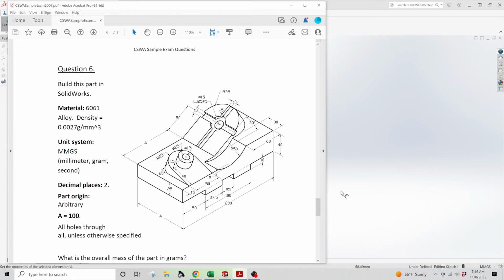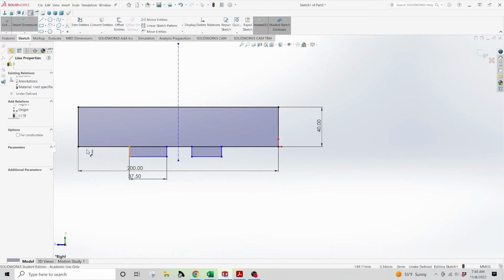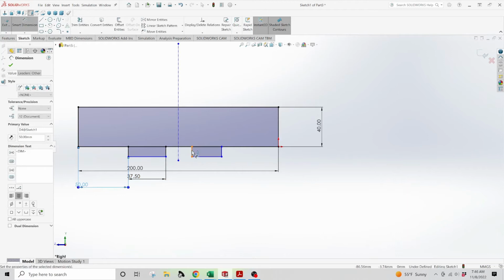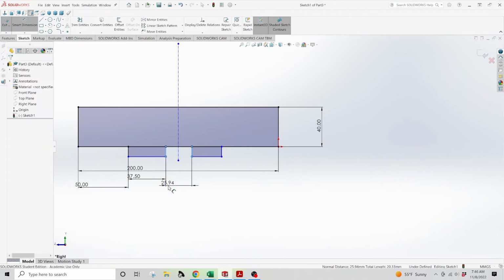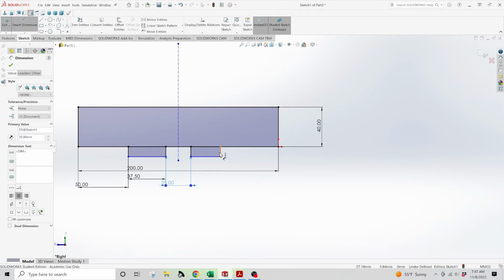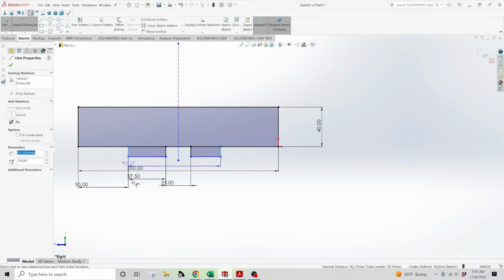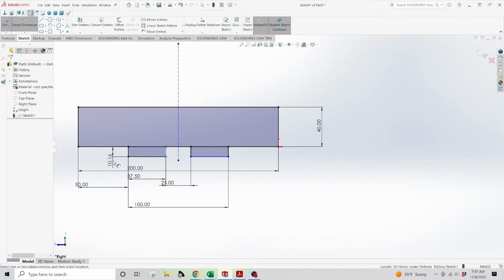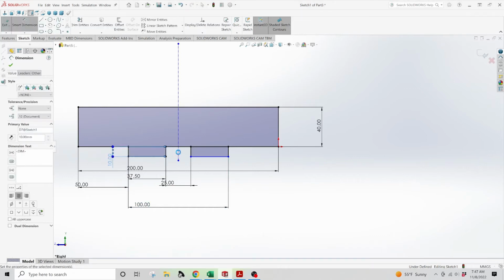This edge is 50 millimeters from that edge. So here to here should be 50. So we're close, but not quite. This separation needs to be 25. So again, we're close. And this edge to this edge needs to be 100. So again, we're close. All right. So those two do appear to be the same size, and they should be based on 75 divided by 2, but you want to double check based on other references because they won't always give you nice symmetry in that way. So that's an important aspect, and these are 10 millimeters thick.